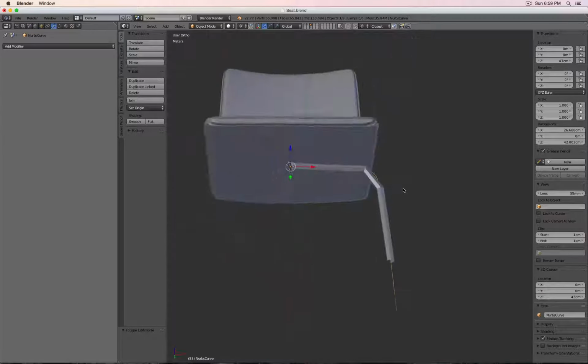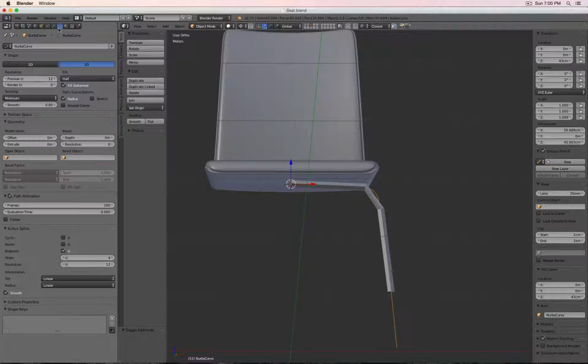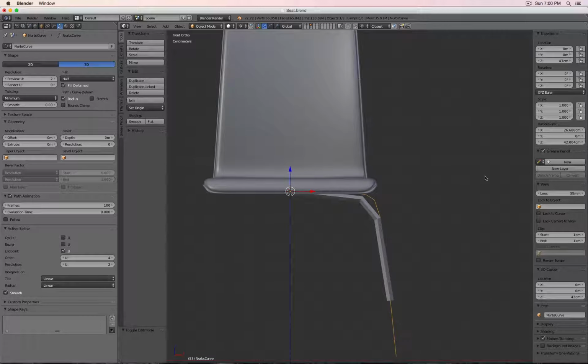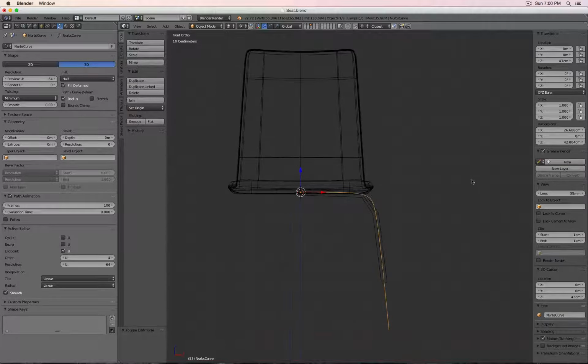So there you see that the pipe bends, but because I don't really have many polygons or subdivisions, there's not much geometry this deformer can perfectly deform. Also, forgot to say this, maybe set this one to something like 64. What this does is it's kind of like a subdivision or accuracy for the pipe. Now everything I'm doing here right now is not very precise in terms of engineering. I'm simply building quickly a pipe which is easier to manage, to model, and also very good for rendering.